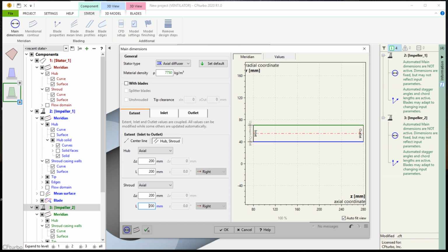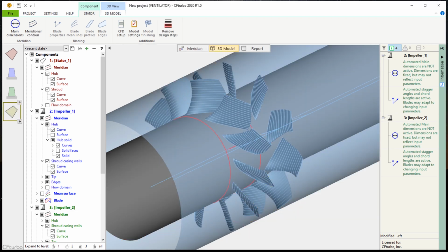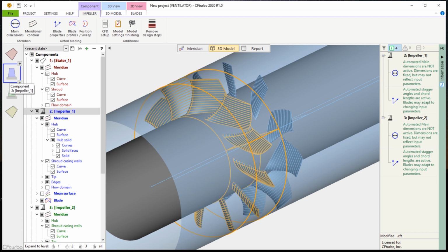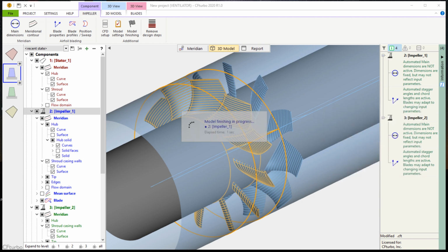Components like pipes or guide vanes. The inlet pipe should have a certain length in order to prevent an impact from the boundary conditions to the fan stage itself while running a flow simulation. The outlet pipe should be longer since the wake of the impeller flow should not be disturbed by the outlet boundary conditions.